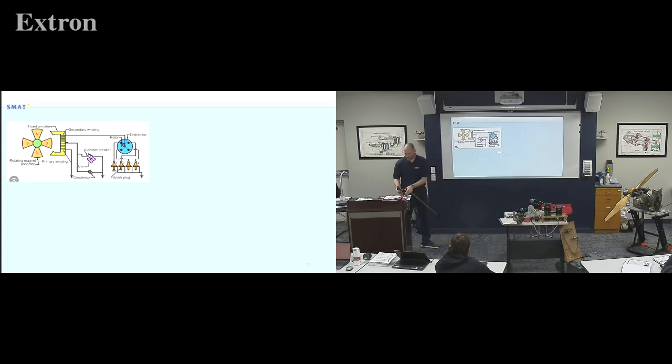And on the other side of that carbon piece on the wheel is a little brass, typically, pointer that's going to run around the inside of the distributor, and it's going to point at whatever wire wants to get sparked. So this thing's going to rotate much slower than the whole magnet on the magneto, right? So every time the points open, he better be pointed at one of the spark plug wires.